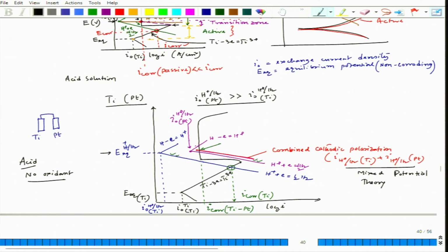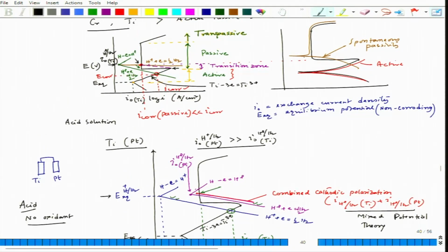Okay. So, now if we do polarization, then we will see exactly similar plots here. In this particular case, we are changing the cathodic polarization kinetics. In case of the brown line, it is actually coming with a much shallower slope, which means its kinetics is enhanced.